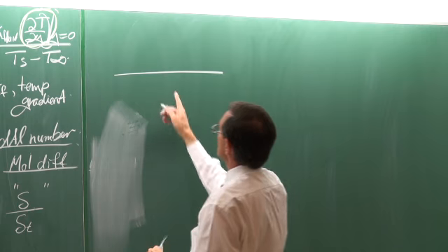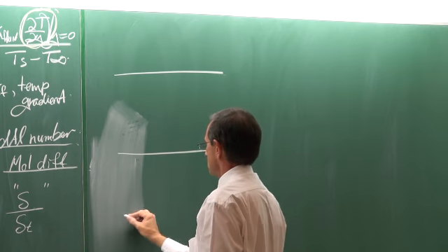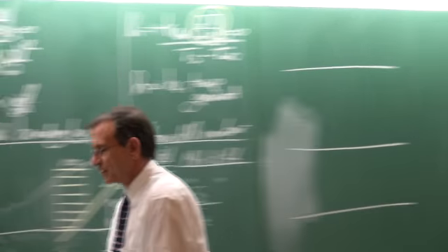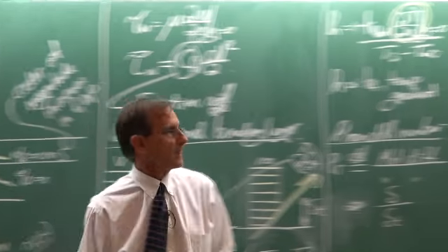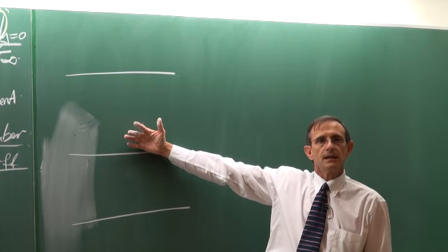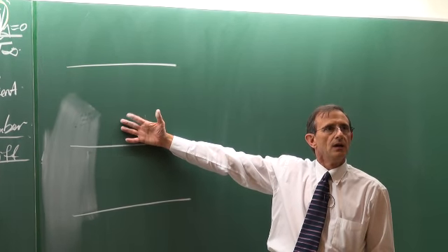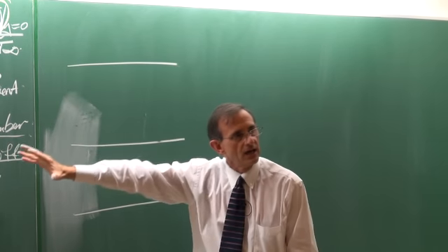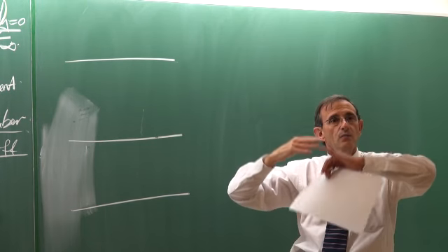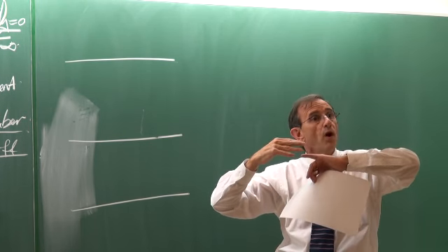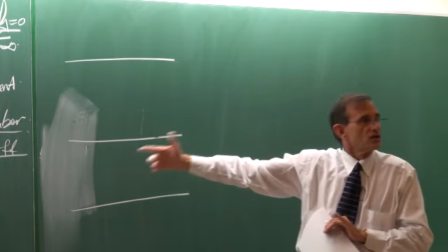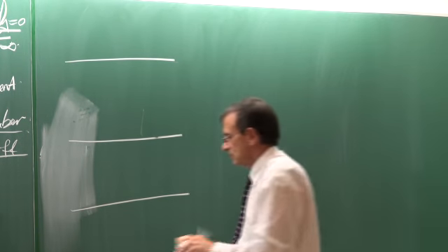And that would be the scenarios on the flat plate. If you have a blue pen and a red pen, then please use them. What we're going to look at now is the different possibilities of the boundary layers. We have looked at the boundary layer, which is delta, and the thermal boundary layer. Now it can be that the one is thicker than the other because of the Prandtl number. So there are three possible scenarios approximately.